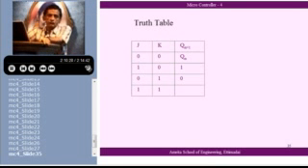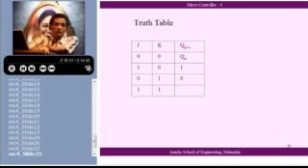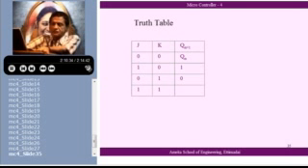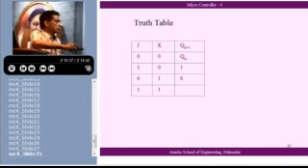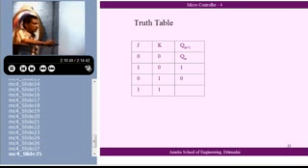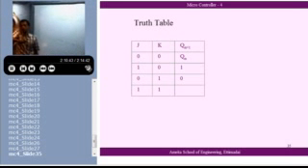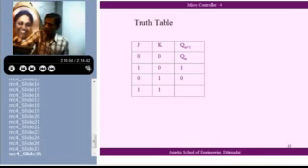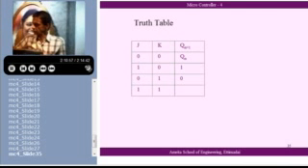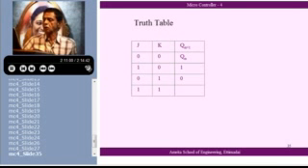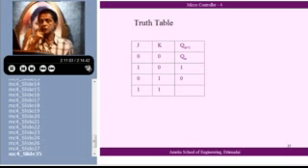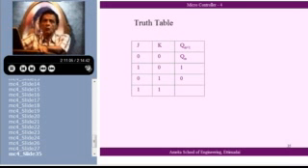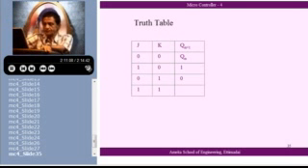First of all, the JK flip-flop will do anything, if at all, only when the clock pulse comes in. Only when the positive pulse of the clock comes, there is any change in the JK flip-flop. If there is no pulse, there is no change, no activity, the memory continues. Only at the time of pulse, any change will come into picture. So all the discussion I do is concerning the pulse and the clock inputs. I have given the truth table here, showing what will happen when a pulse comes into picture.